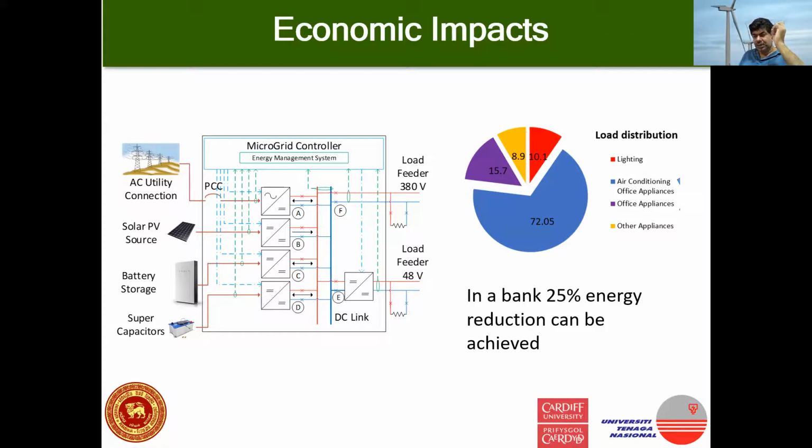So why not, rather than using the present approach where, as I was showing you with EV, you convert the solar power into AC and convert AC back into DC when you are using it, use a DC microgrid where you don't have any AC except the utility grid, which is also connected to DC, where you connect all the bank loads into that DC bus bars.